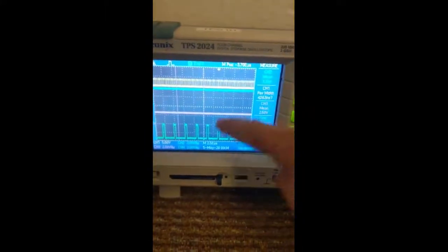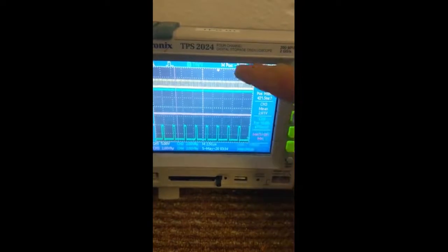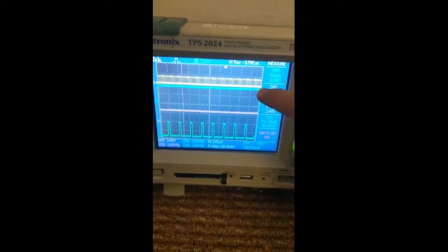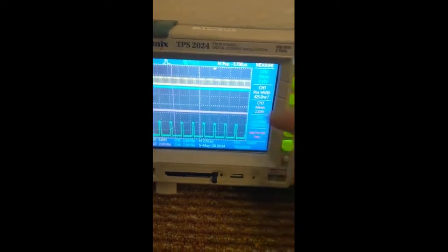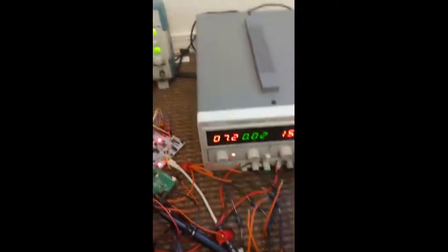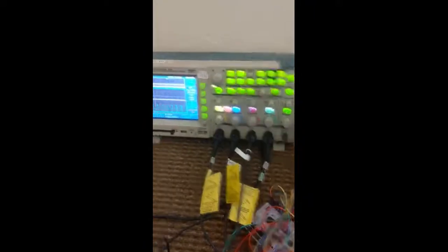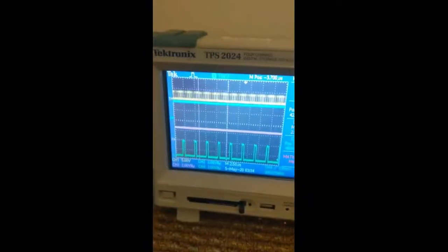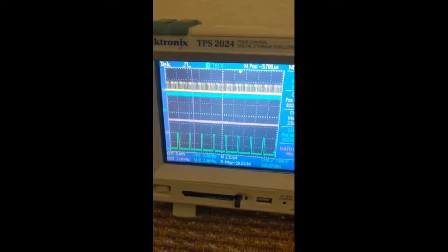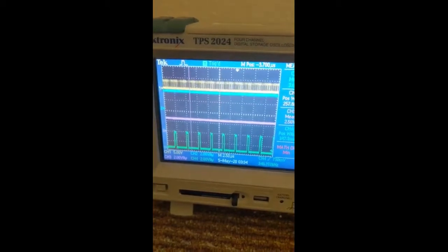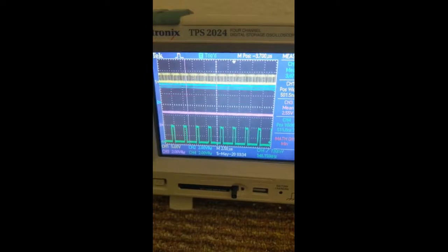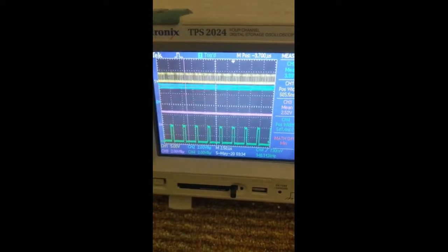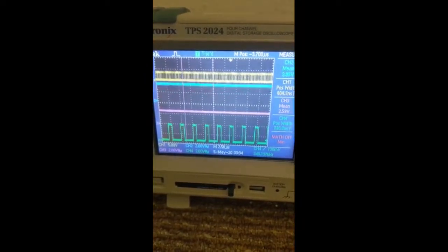So this is converter 1, this is converter 2, this is at 350 kilohertz, this is at 500 kilohertz, this is the signal at 3.19 volts, and the other one is at 2.6 or 2.5 volts approximately. And now if we start giving input voltage disturbances, you can see that the duties of the converters change, and we are actually fighting against the input voltage variations.